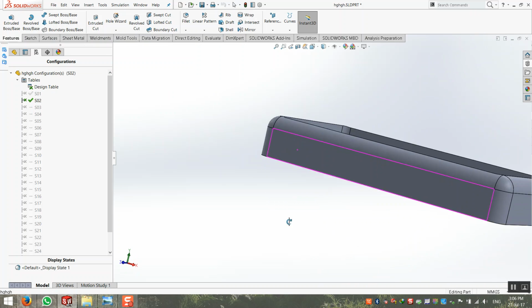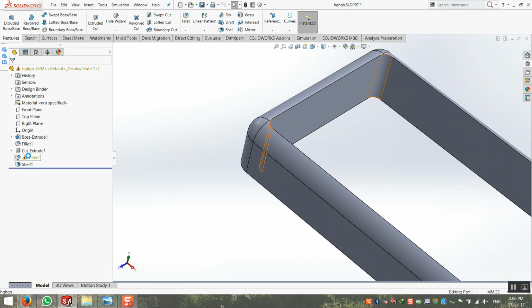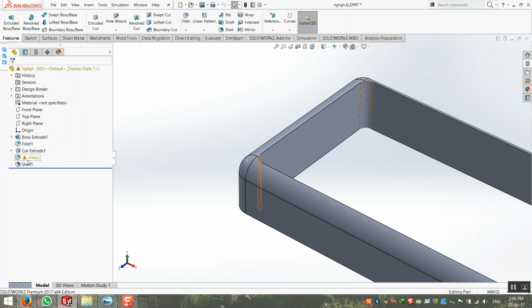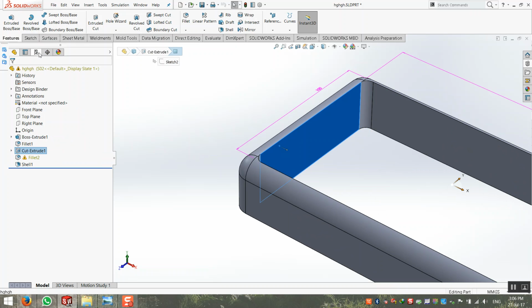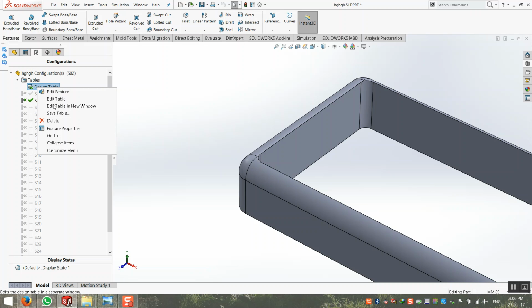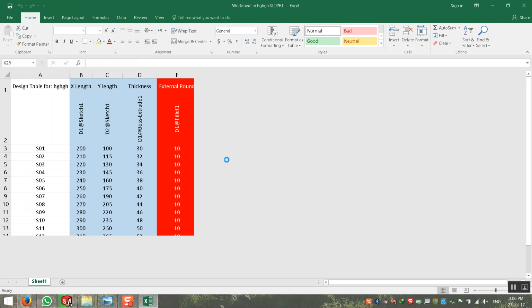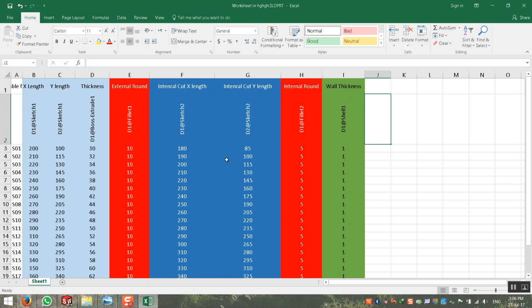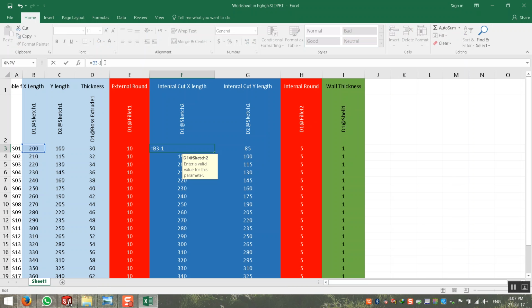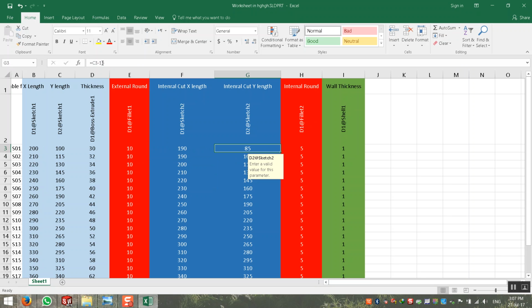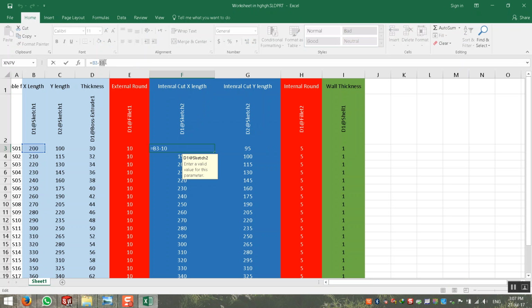Now was very small. This round fillet have a problem because you have here a fillet 5 and the other side fillet 10. Okay, so you need to change. Minus only 10, minus only 5. Okay, no, not 10, minus 30.